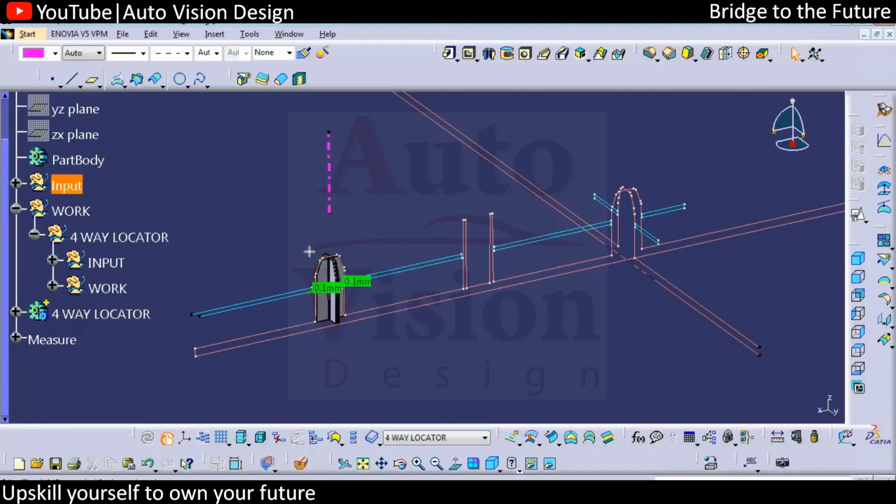Okay, so if you want to create this locator somewhere in this area, again at 4 to 5 places, we can create this with the help of the power copy. It might be instances 1, 2, 3, 4 in the same part or in another part. Further, we can save this power copy separately and recall it for another part. So this part 2, part 3, part 4, in that we can add this particular locator profile.